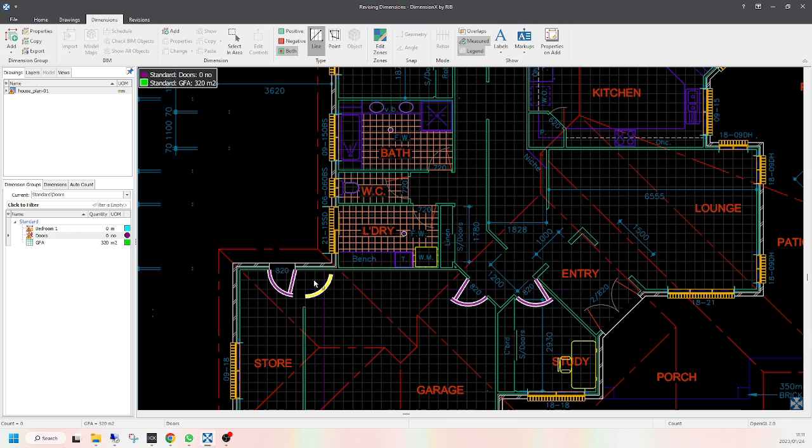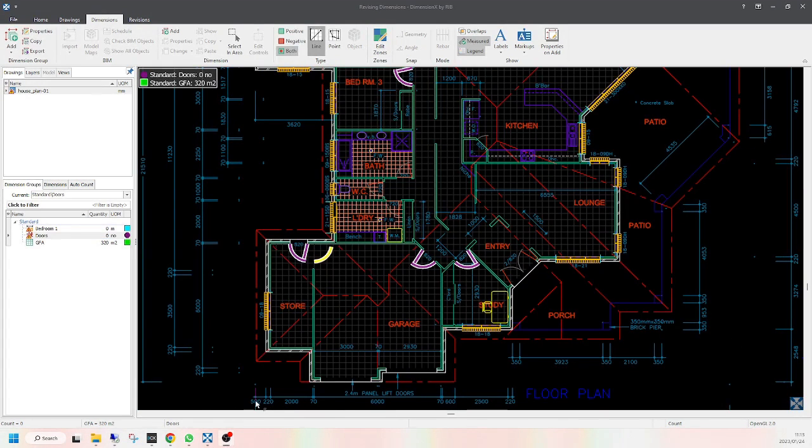In the revision mode, the sticky cursor attaches itself to the center of a count dimension. Count dimensions can be selected and moved by clicking on the dimension while the sticky cursor is attached. When the dimension is moved to a valid location, it will snap to the location on the drawing. To deselect a count dimension that is being moved, press the Escape key on your keyboard.